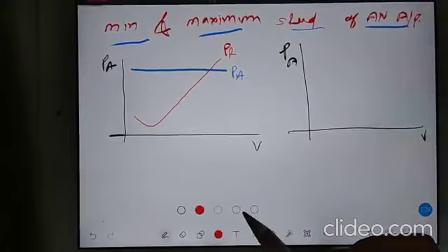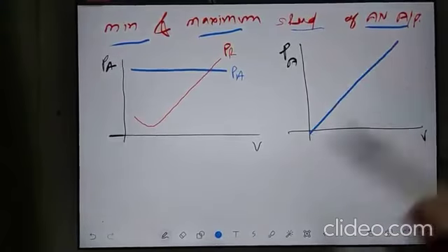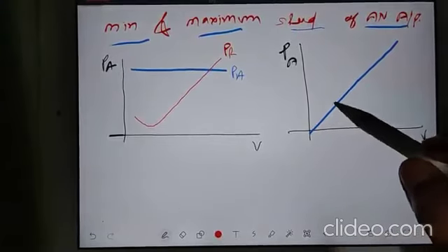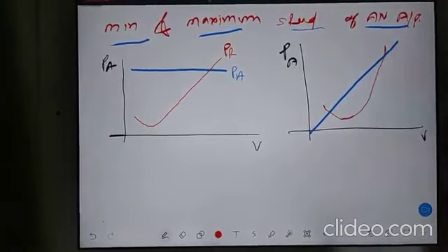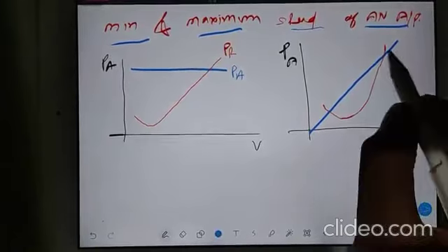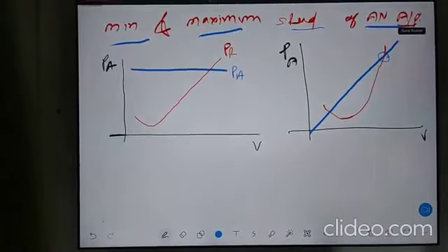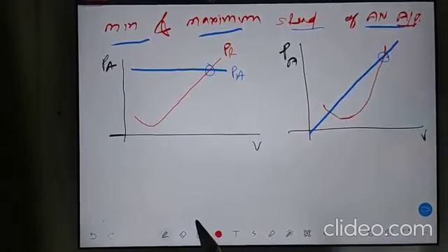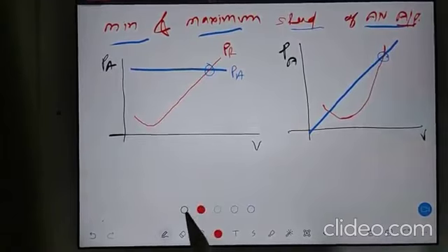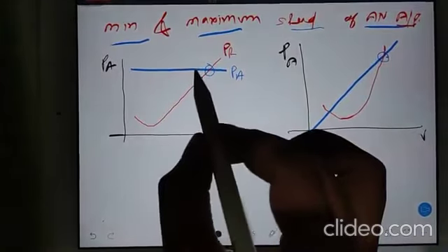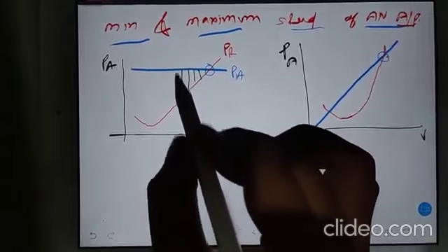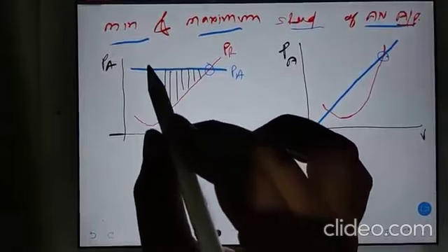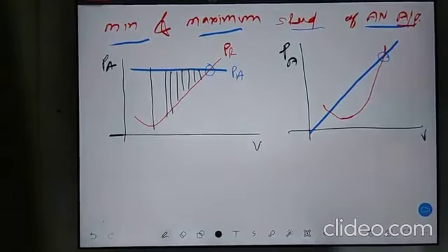So another diagram, power available and velocity. Now I am drawing this diagram and power required is the same, and you must cut this point. Okay, you must cut that point, and here also you must cut this point. You should not draw a smaller line, you should draw such that it cuts. Now you compare. Here you have the maximum gap, maximum gap, maximum gap.